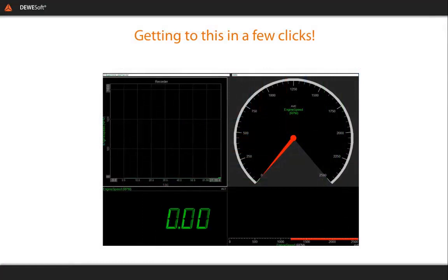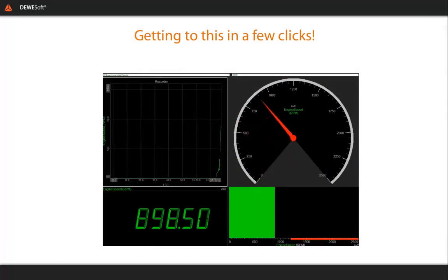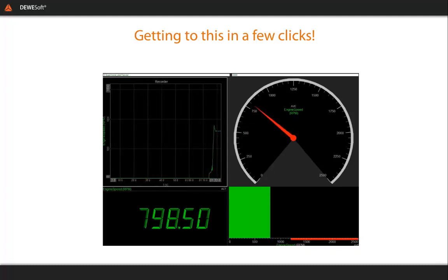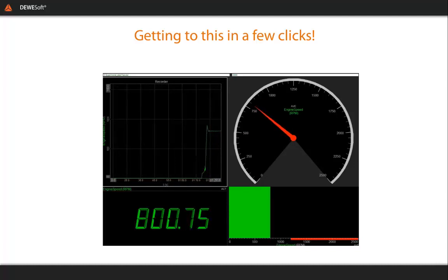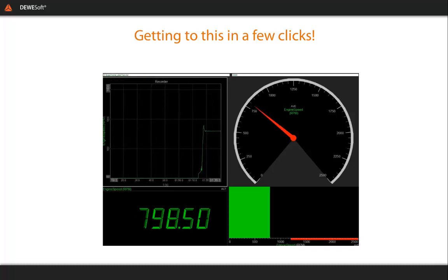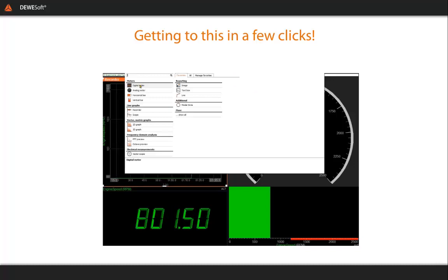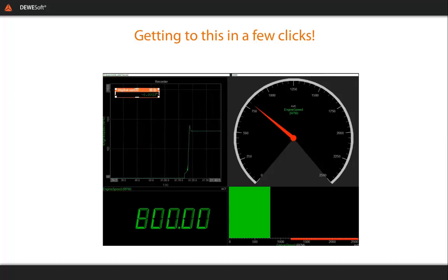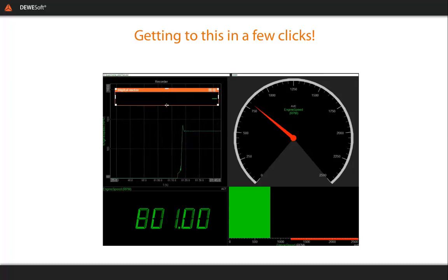Now we'd like to wrap this up by starting with a video of some data, then showing you how easy it can be to get to this from your CAN signal in as few clicks and as little effort as possible. So you see here a video playing which is just actually monitoring engine speed from an SAE J1939. And you can see the engine start and you can see it idling. And we've just set up a very simple display just to show that, and we're going to manipulate that in just a moment. So here we're adding a digital meter in, and this digital meter can actually show the hexadecimal values as they're coming through the bus. So we'll move on.